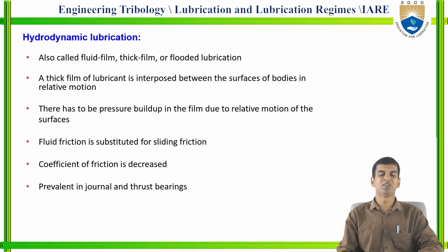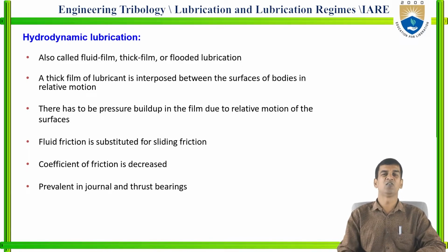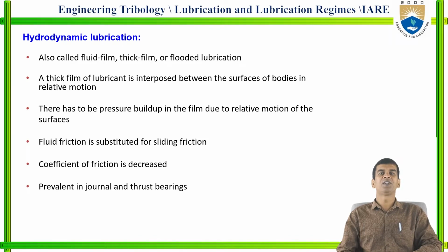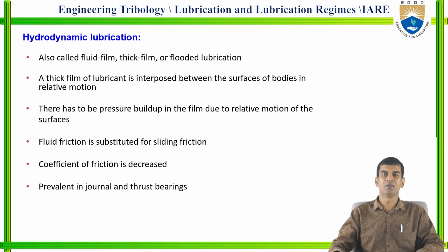There has to be pressure buildup in the film due to the relative motion of the surfaces. You have a thick film of lubricant between the surfaces in hydrodynamic lubrication, and because of that, pressure is built up between the surfaces. Fluid friction is substituted for sliding friction.